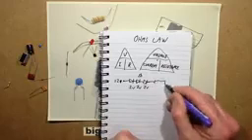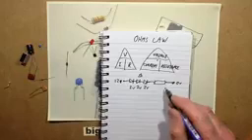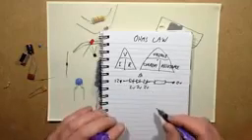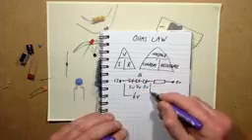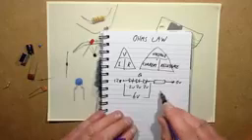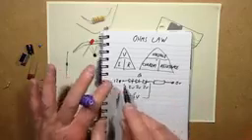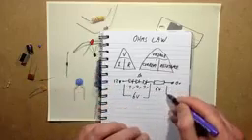You want to choose a resistor that is going to limit the current through these LEDs to 10 milliamps. So across the LEDs, you've got 6 volts dropped. Across the resistor, because it's a 12 volt supply, you're going to have 6 volts to drop.